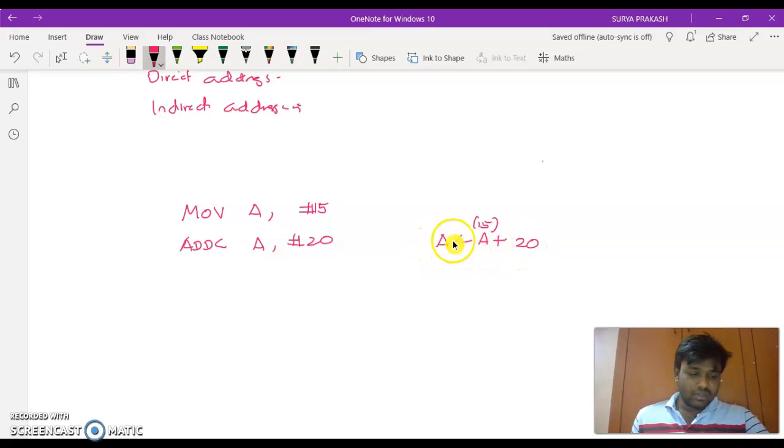Here you must know the numbering system used inside the program. We'll be writing the hexadecimal addresses over here, and for each and every address, this value will be loaded. These values are all denoted in hexadecimal format. Unless you indicate decimal, octal or binary format, it won't be reflected inside the controller. So by default it will be in hexadecimal format.